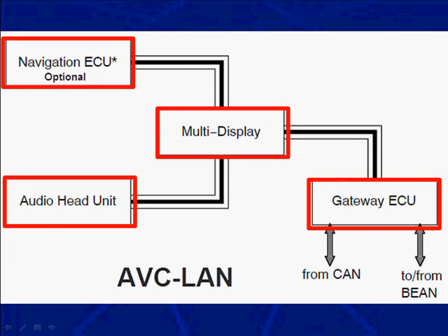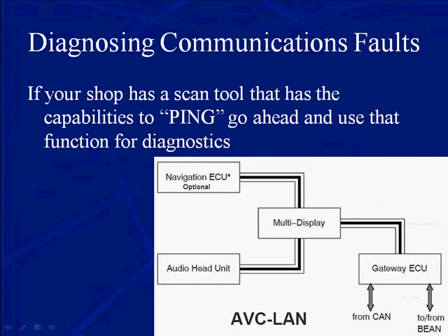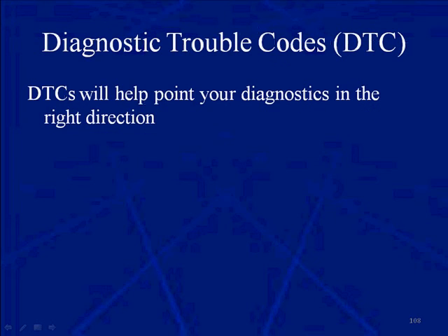Or are we on regenerative braking? So that's why they're connected through the gateway module. Diagnosing communication faults. If your shop has a scan tool that has the capabilities of ping, go ahead and use it. That is a great function for diagnostics. If your scan tool pings, ping.